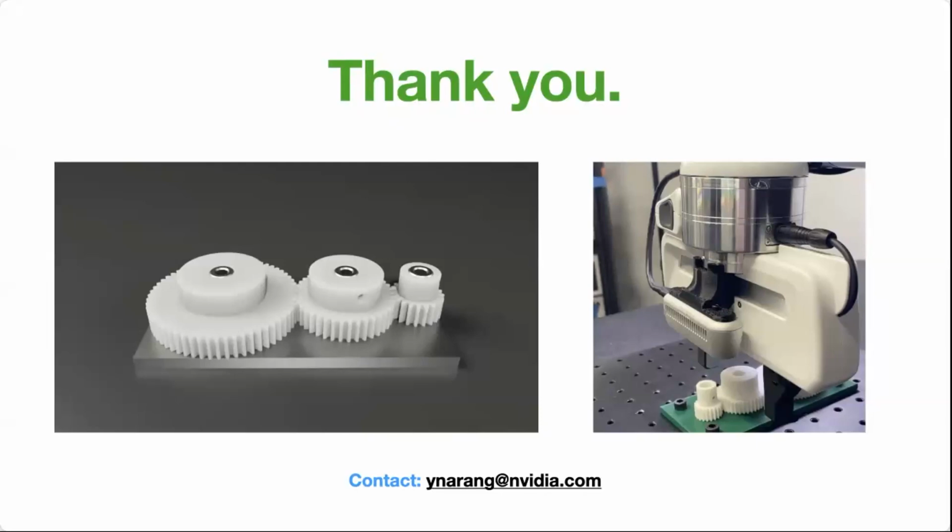And one more question. Did I hear a 4.2 millimeters error? Yeah, that's a good question. For specifically reach tasks with the robot, we were able to achieve about 2 millimeters of error. And when we were running experiments for the paper, we were doing this laser pointer experiment, which had not only error due to control or due to our policy, but also error due to perception. That combined was 4.2 millimeters of misalignment error.